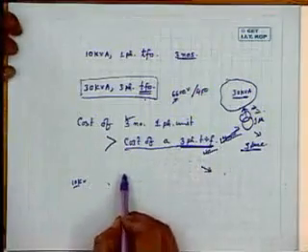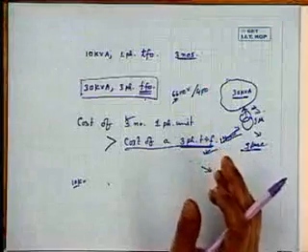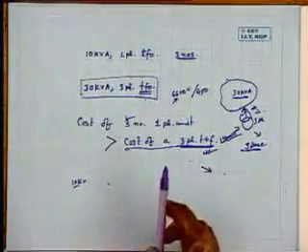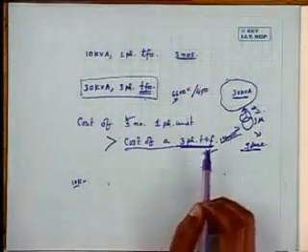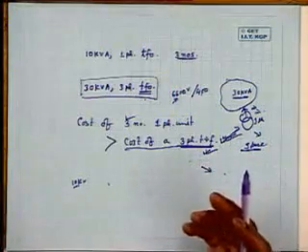Are you getting? But with a three phase transformer, once a single phase transformer becomes faulty, you switch off the power, only take out that single phase transformer, the other two are okay. But that you cannot do with a three phase transformer. Because of what? A three phase transformer is a single unit.